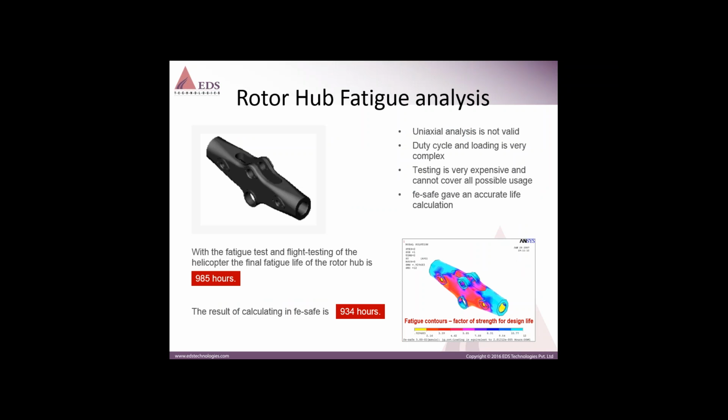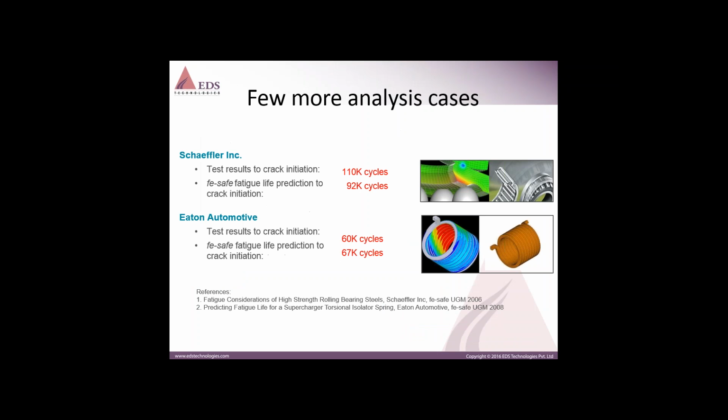So FESafe is the solution, and you can see here the correlation between testing and FESafe. From testing, it took nearly 985 hours to generate a crack, whereas FESafe predicted the crack generation at 934 hours. Similarly, we have a few more cases of FESafe giving a very close result to the tested result.